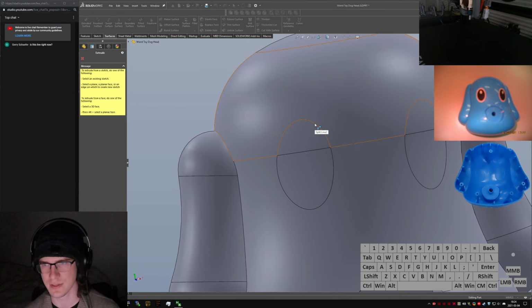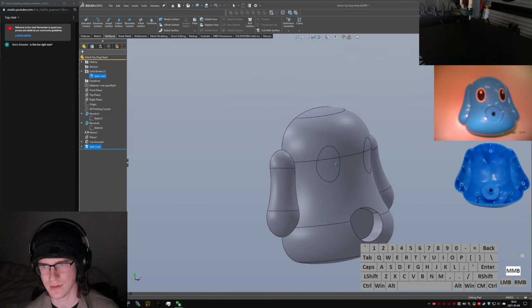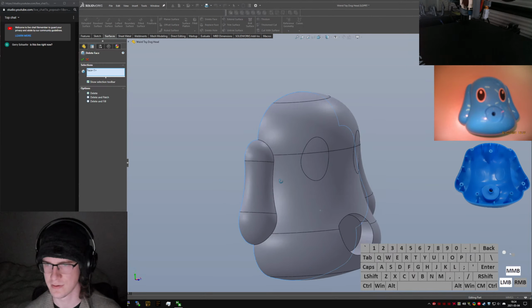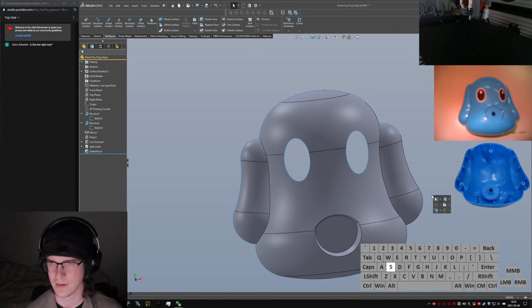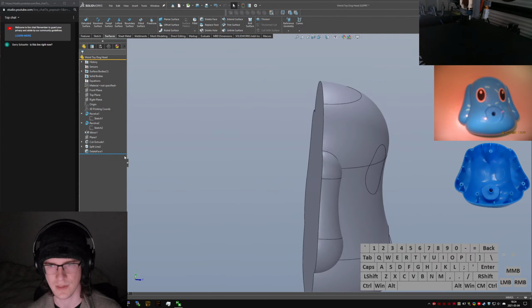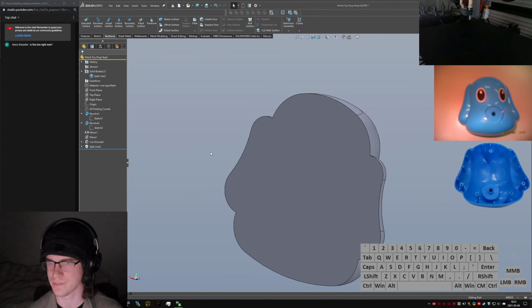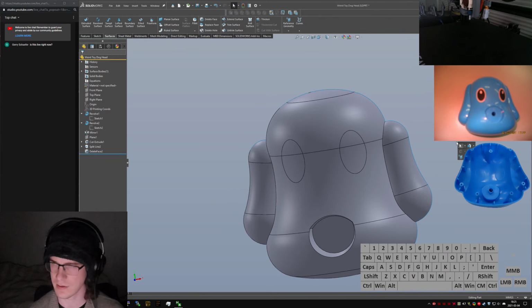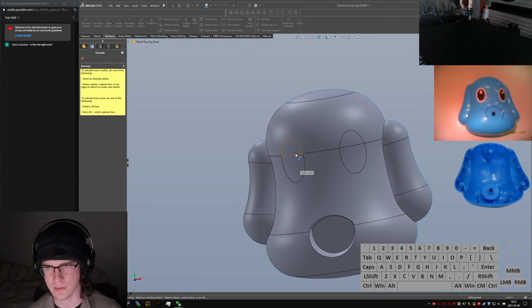What I want to do is... Alright. We're getting nasty here. We're going to start deleting faces. Extruded surface. Alt, to extrude from a face. Oh, select a 3D face and press Alt to select a planar face. So maybe I want to delete just the back face to make this a surface body, and then do an extruded surface.